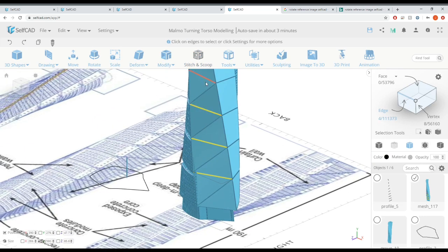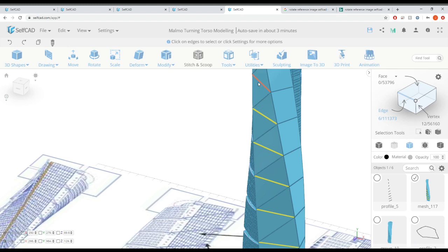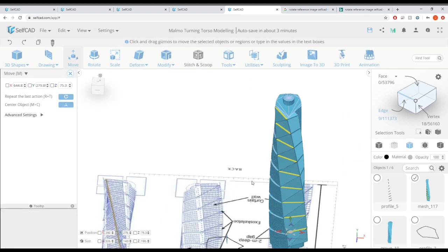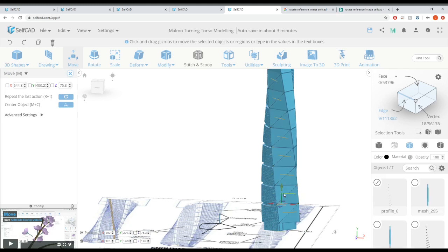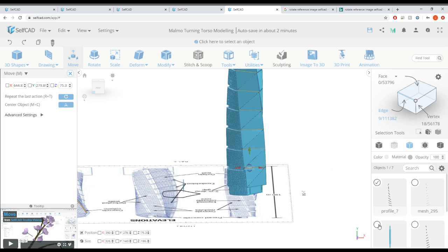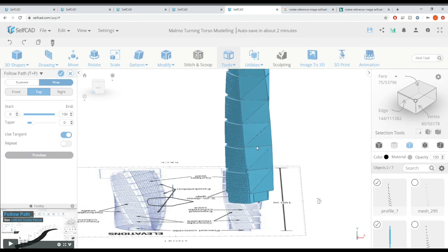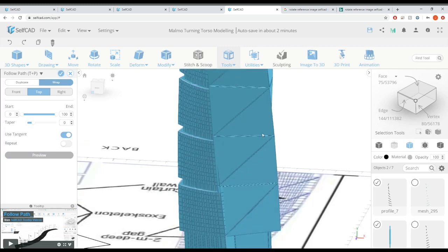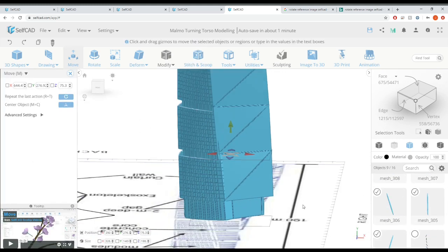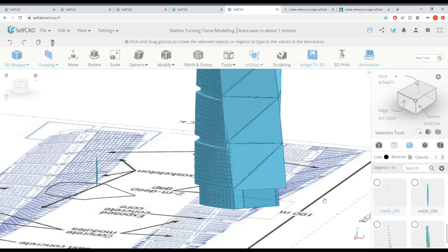And we're going to merge those objects because we have no need for them to be separate objects at this moment. And what we're going to be doing is we're going to then select the horizontal structural elements, and we're going to do the same for these horizontal sections by copying it down, using the move tool while holding control, and then actually bringing it back up to where it was. And then we're going to select these lines together with the cylinder that we drew just now and hit follow path.